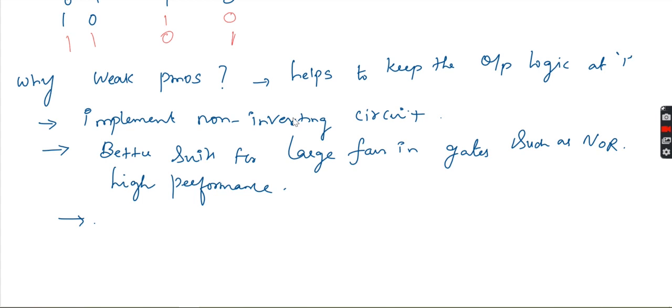Next, the output of the gate is sometimes pre-charged only to discharge in the evaluation phase, so the signal activity at the output can be high.